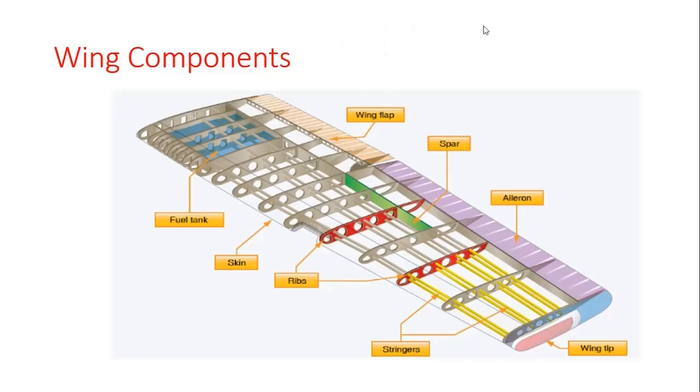Next, flaps extend outward from the fuselage to near the midpoint of each wing. The flaps are normally flush with the wing surface during cruising flight. When extended, the flaps move simultaneously downward to increase the lifting force of the wing for takeoffs and landings.